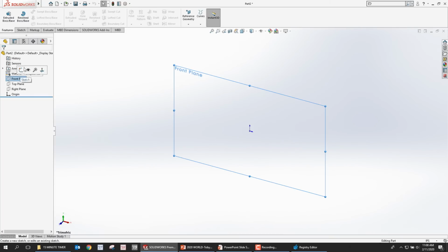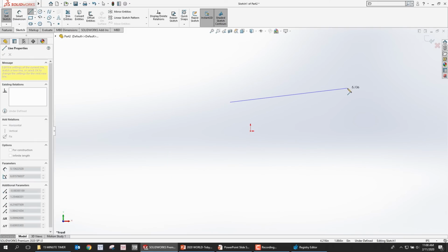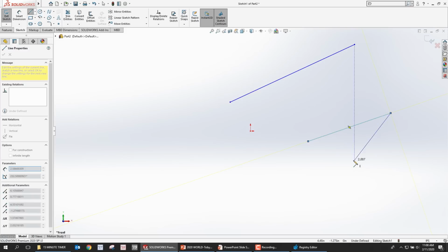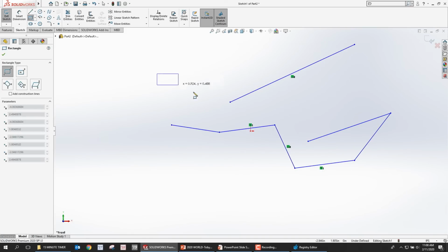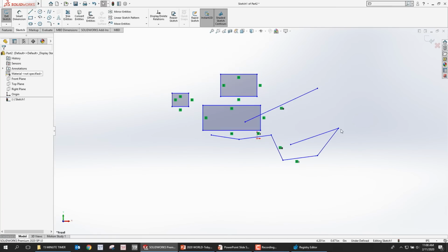So these 2 ways of doing this are, you can take the line command and you can single click and drag and move over and then let go. So I'm holding the button down this whole time and then I can let go. Or you can click, move your mouse, click again, move your mouse, click again, move your mouse. Okay, there's 2 different ways of doing this. I think a lot of people who use SolidWorks know this. I think this is pretty much a beginner tip, but I think it's good to know that the main one that's different is lines.